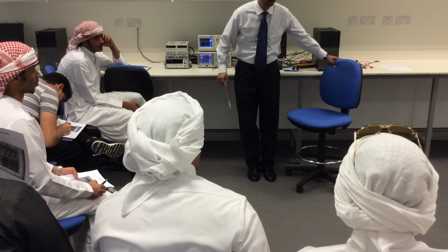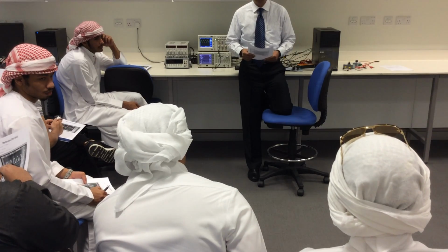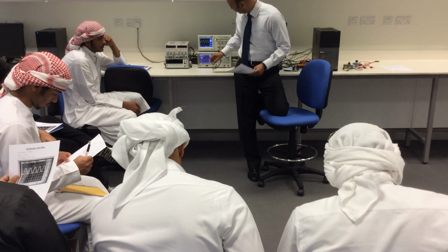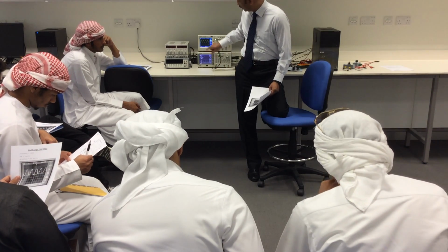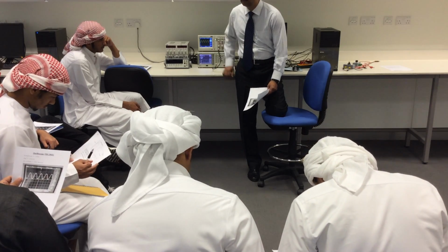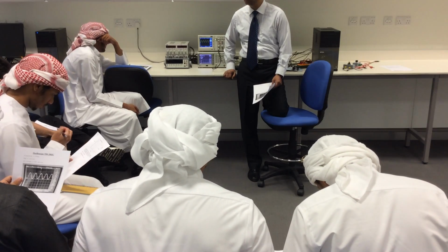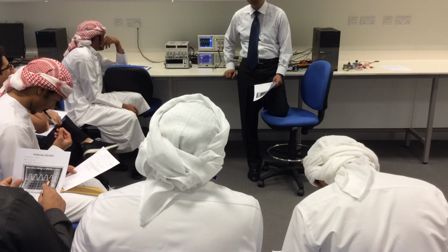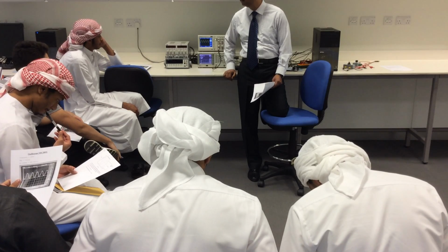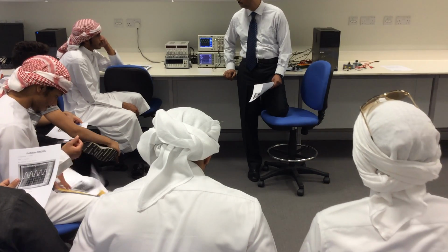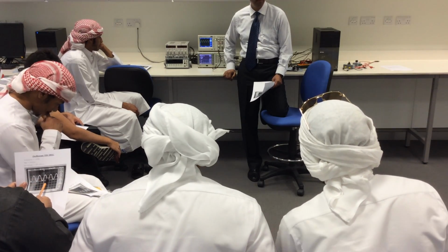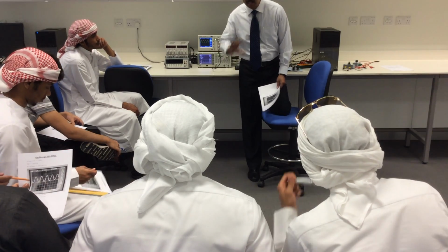Everyone? Yes. Now, each block on the time axis represents how much? 5 millisecond. So if you want to find the period, how many blocks do we have in the period? We start from 1, 2. So that comes to 10 millisecond. Is this the period of a 100 Hz frequency? Yes, 1 over 100 is 10 milliseconds. So the frequency is right.